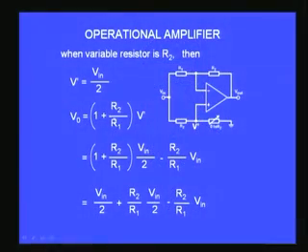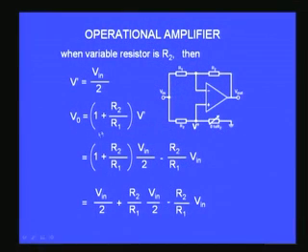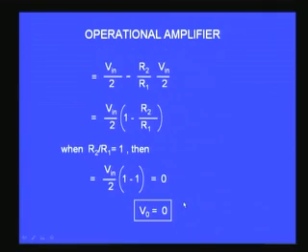So when that happens, what is the voltage gain? The voltage gain for the non-inverting amplifier is 1 plus R2 by R1 times the input voltage. The input voltage here is not the actual Vin that we have applied, but V prime, which is the effective voltage after the potential divider applied at the non-inverting terminal, and V prime we have already seen is Vin by 2. So if I substitute that and simplify, this is the gain corresponding to the non-inverting terminal, and then there is also the inverting terminal always present, therefore that will give minus R2 by R1 times Vin. So the total gain of the amplifier, when you simplify, becomes